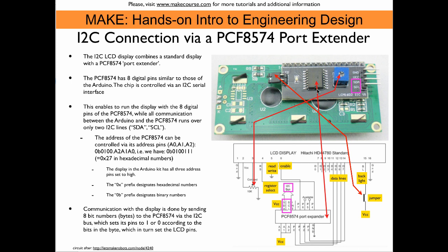The most important part on the module is the PCF8574 port expander, and this chip essentially is controlled through the I2C bus, so it's directly connected to SDA and SCL here. It has all these pins that essentially function like Arduino digital pins.